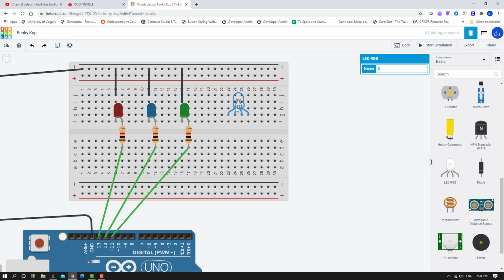placed inside. So we're going to return our cathode by clicking on the pinhole and dragging a wire or jumper wire up to our negative return line. We're going to color that black. And then we're just going to simply match this to these pins here so we can see sort of how these turn on and how the light here changes. So let's go ahead and drag another pin out from pin 13. We'll drag it there. We'll go from pin 12 and we'll go from pin 11, sorry.